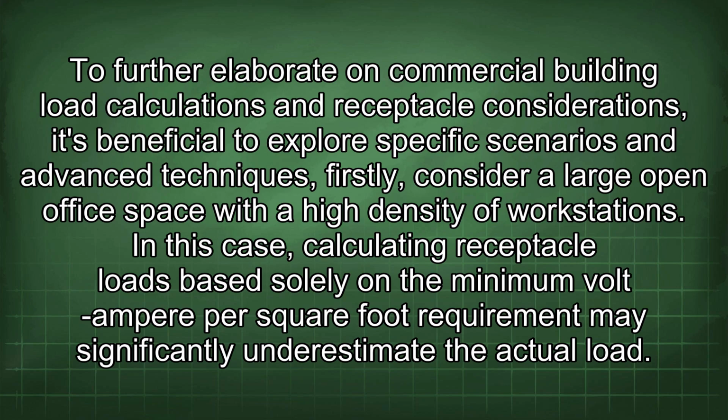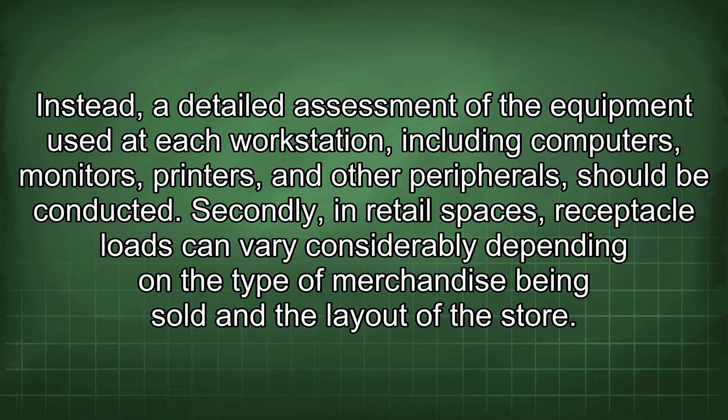To further elaborate on commercial building load calculations and receptacle considerations, it's beneficial to explore specific scenarios and advanced techniques. Firstly, consider a large open office space with a high density of workstations. In this case, calculating receptacle loads based solely on the minimum volt-ampere per square foot requirement may significantly underestimate the actual load. Instead, a detailed assessment of the equipment used at each workstation, including computers, monitors, printers, and other peripherals,